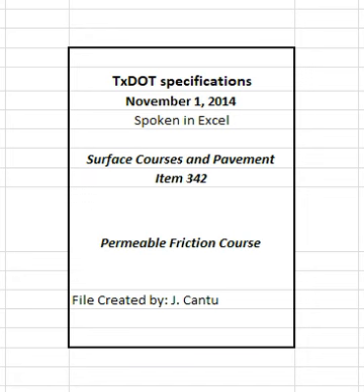4.4.2.2.3 Conditional approval of JMF1 and authorizing trial batch. The engineer will review the contractor's mix design report and verify specification conformance of the mixture and component materials. The engineer will grant conditional approval of JMF1 within 2 working days of receiving the complete mixture design report, JMF1, and all required materials.